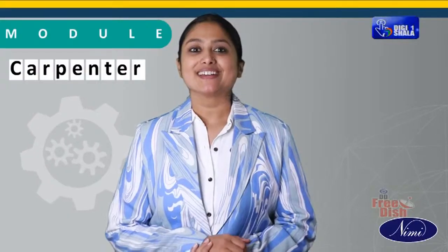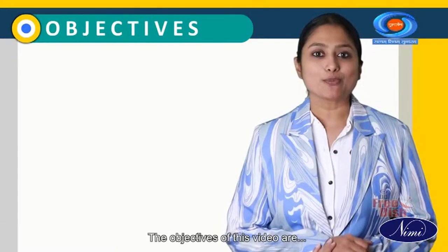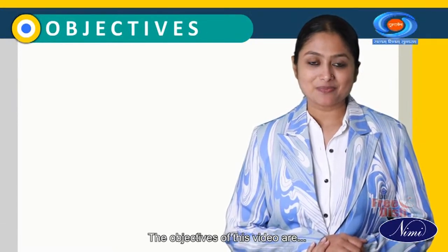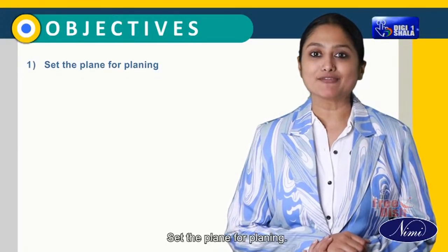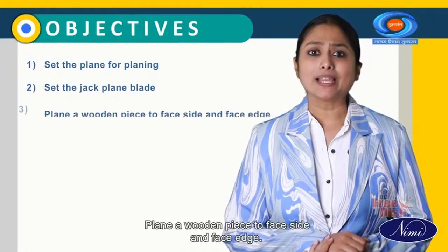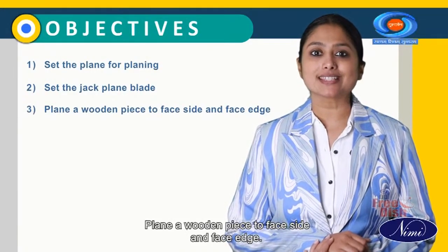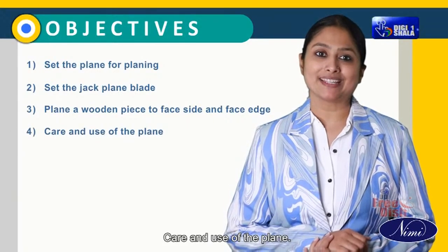Hello trainees. Today we are going to learn the use of jack plane. The objectives of this video are: after the session you'll be able to set the plane for planing, set the jack plane blade, plane a wooden piece to face side and face edge, care and use of the plane.